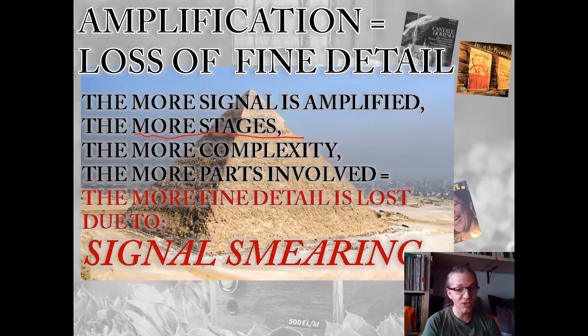Because in audio, the THD and active distortion that the amp adds to your system is just one part of the distortion. When we think of distortion, it has two sides. On one side of the scale, you have this additive distortion that we measure as harmonic distortion. There are other types of additive distortion, not just harmonic, but those are really difficult to measure and they are not measured. So maybe your equipment has a super low level of harmonic distortion, but its non-harmonic distortion might still be really high. And that's the case for solid-state amplifiers. We'll have a look at that later on. But anyway, when you measure added distortion, we have a pretty good idea about that, at least of the harmonic component, how that works. But there's also omission.